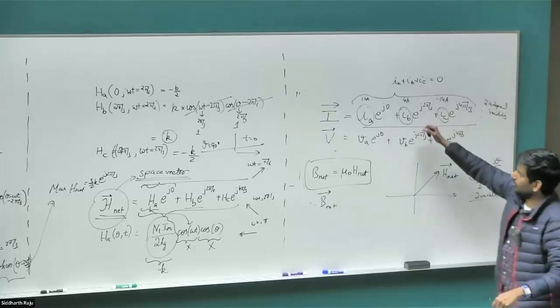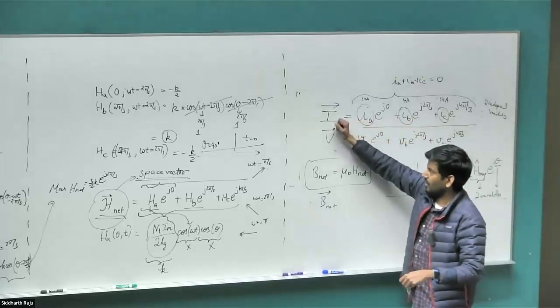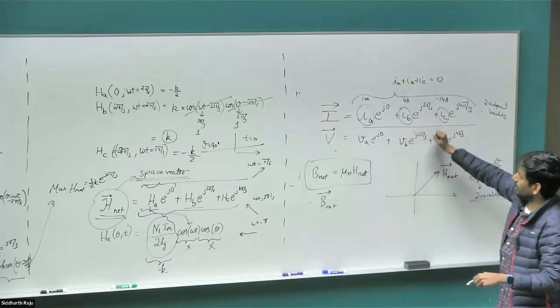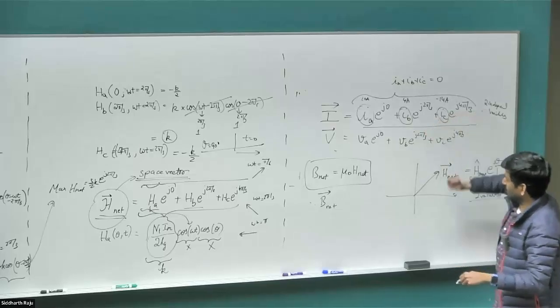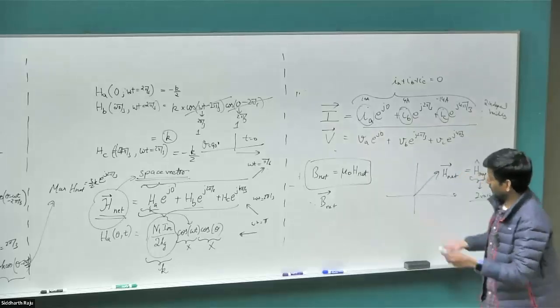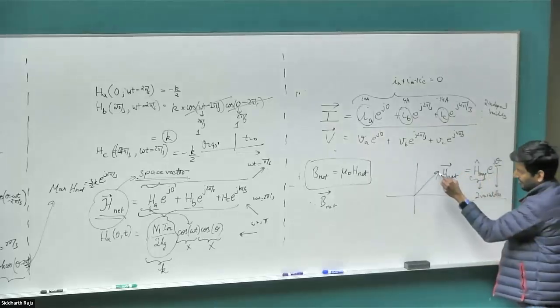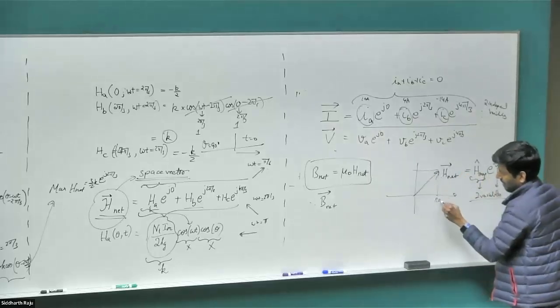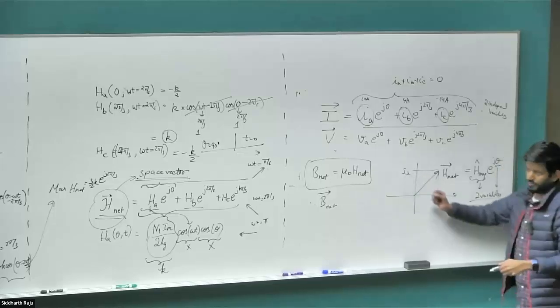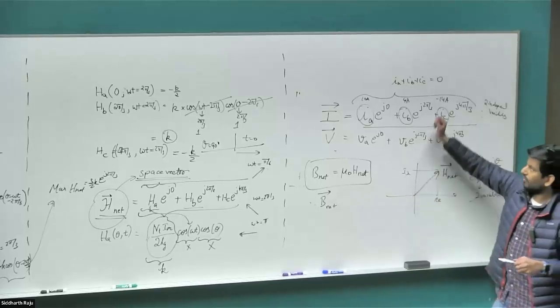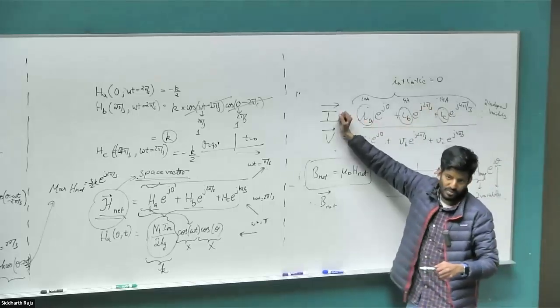So when I plug it into this and transform it into some other variable, as long as the independent variables are conserved, so here I have two independent variables. In the space vector domain also I have two independent variables, either the magnitude and angle form or the x and y, real value and imaginary value form. Either way I have two independent variables that I can control. So going from this space to this space, I'm not losing any information.